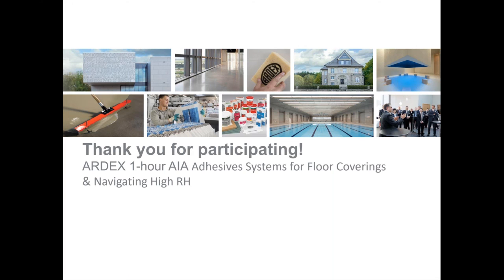Well, I'll say this: the industry standard for resilient flooring is F3010, and that standard details the use of a two-component membrane-forming mitigation system. So there's an industry standard that makes that recommendation. From my experience, and looking at the industry itself, there are multiple manufacturers that make two-component resinous materials.